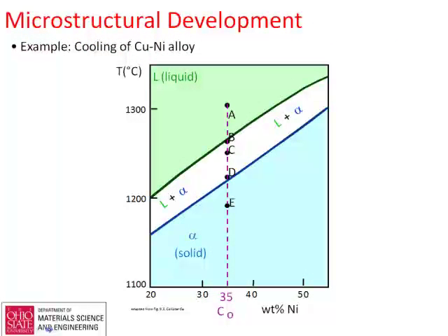The thing I do want to get through, though, is that there is an interesting microstructural development, very similar to what you see on a cold winter day when you put a little wiper fluid on your windshield. You see these dendrites form. You see a first bit form, and then it pushes solute off to the side.